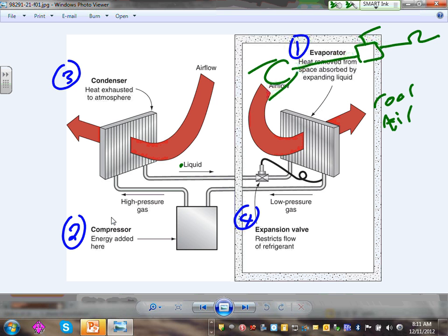Now, how do we move the air through the refrigerant? We move it through a blower. This is where we interface. We come in as electrical. We throw the air, so inside the building you have to have a blower. The blower is going to blow the air right through that so-called evaporator. The evaporator has the refrigerant going through it. It picks up the heat from the air, right? From the other end you get cold air.